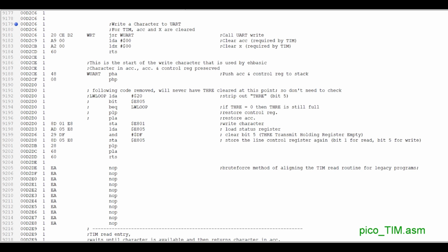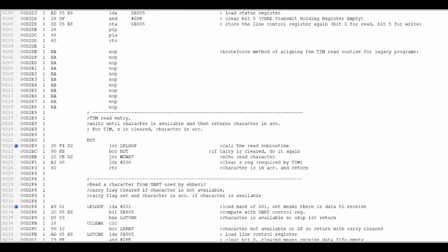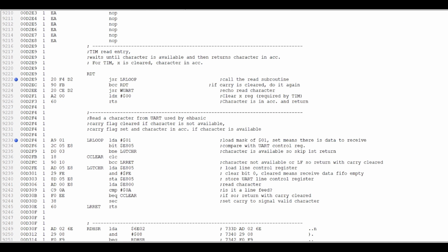Since the RP2040 UART0 is now doing all the dirty work of timing the serial connection, the routines can be much simpler. I'll overwrite them with the new routines and have enough space left over to add a non-halting character input and customized character output routine for additional programs like EHBasic. I'll share those new I/O routine locations shortly.